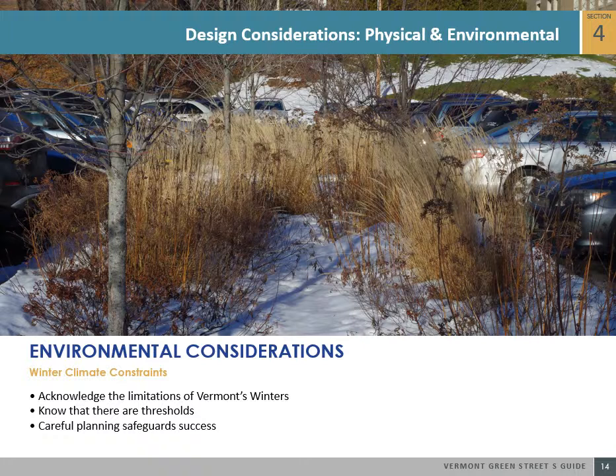An important environmental consideration for Vermont green streets is the winter climate. Vermont's winters can limit certain green street applications, but clear knowledge of thresholds and careful planning can safeguard success. Identify the soil's frost depth and install below it. For most of Vermont, the depth of frost protection is 5 feet.